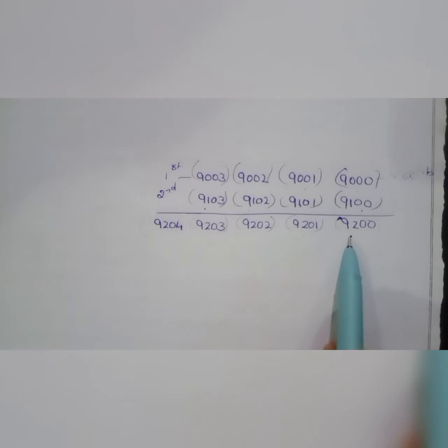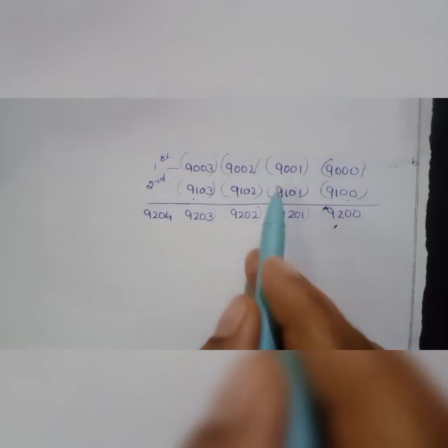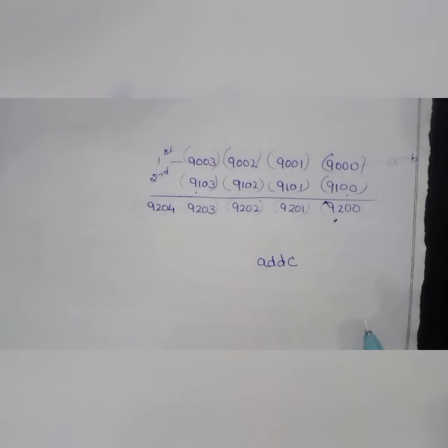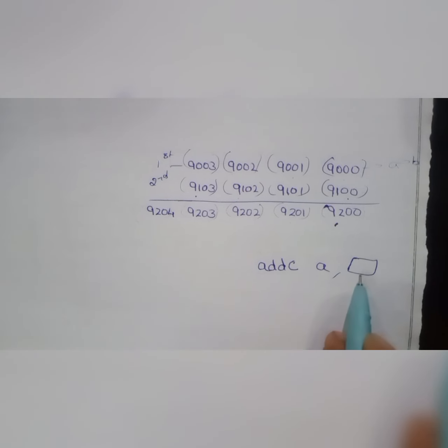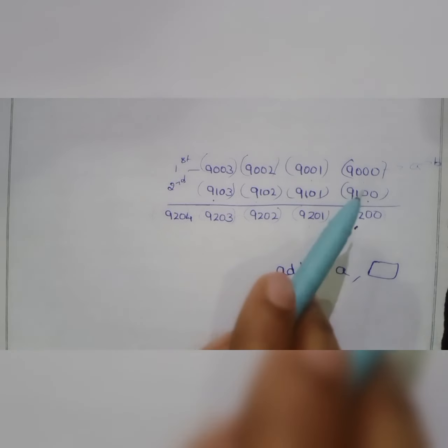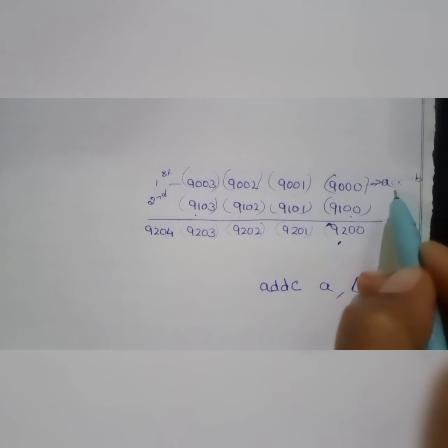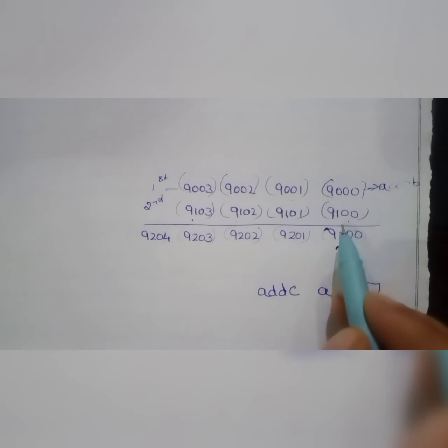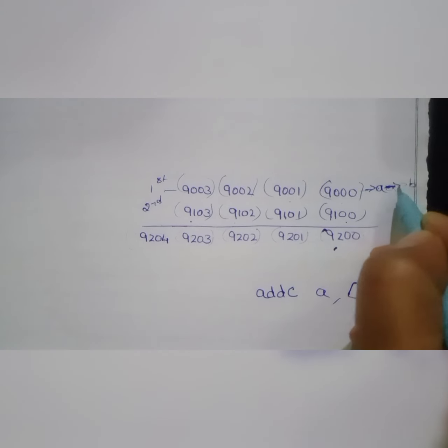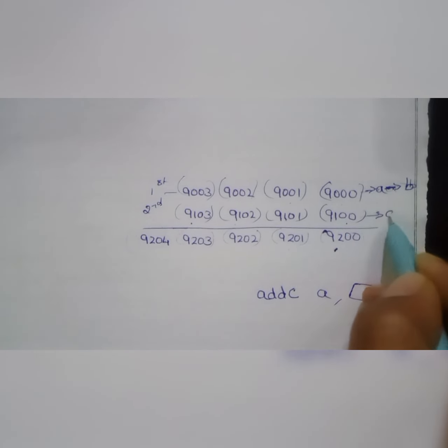As we know, in the assembly program of 8051, the instruction to add is ADD. As we have to add along with the carry here, we shall use ADDC, and compulsorily A should be the destination register, and the source can be a register, direct address, indirect address or an immediate value. So what shall we do here? Let us copy the data present in my first memory location, 9000, into A. As I want the same A register for the next data, we shall copy this to the register B, and the next data to be added, let us take in the register A.